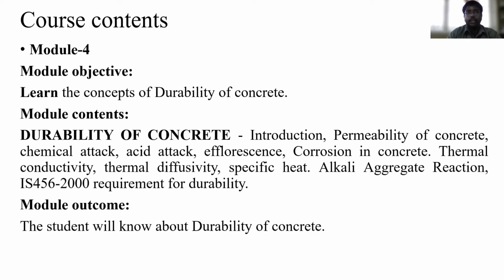So, the concrete which we design and give the shape of a structure should resist all the adverse effects of the environment and should go on for its serviceability or life period. If the concrete deteriorates before its lifespan due to adverse effects of the environment, let us say chemical attack or acid attack, or due to corrosion of the embedded steel reinforcement or sulfate attack, we need to study its process and how we can protect concrete structures from the deterioration process. It is all studied under the process of durability.